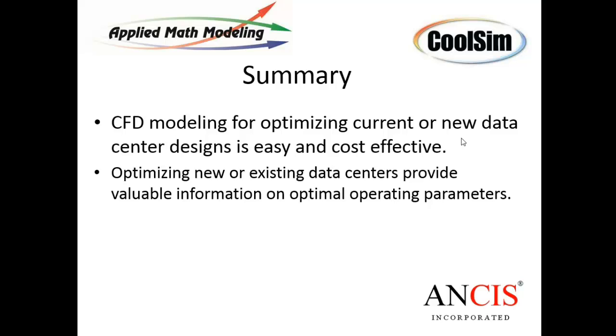In other words, we've done this model, and one could argue that it's an oversimplification. But Hugo and I go into that data center, we know roughly where that crack should be set in terms of flow rate. We know roughly what that RTI should look like. So we have a place from which to start. It may not be exact because the real world is not exactly what we've done in the models. The models assume some ideal conditions. But at least we have a good place from which to start. A lot more than we knew without it, which is we had no data, right?